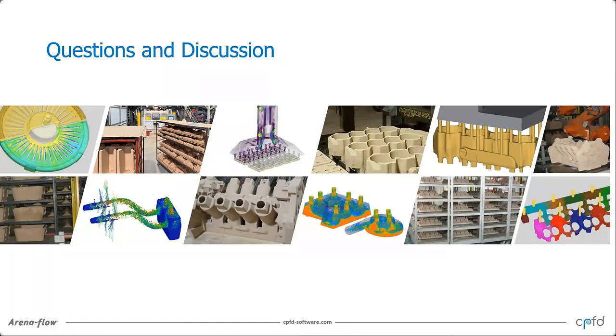And that's really enabled by the new ability to take results from one simulation and use that as a starting point for a second simulation, or a third, as Thomas showed. The other part of that is not just looking at how the core fills under a double blow scenario, but what's happening to that sand shape in the magazine, which can lead to insights into the magazine itself, or strategies when filling, or really how different fill levels affect the blow.